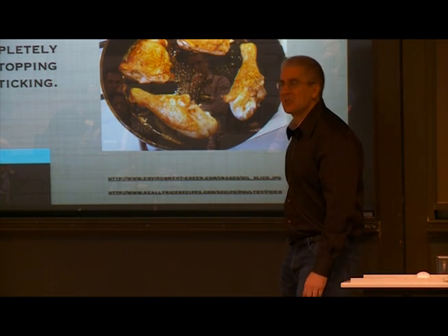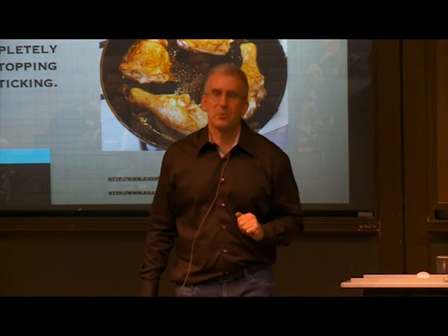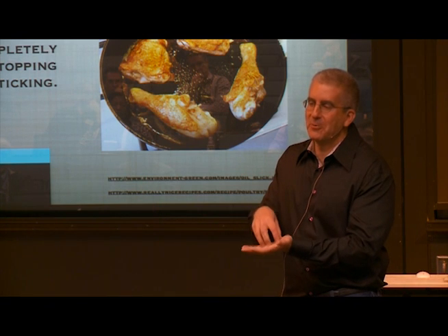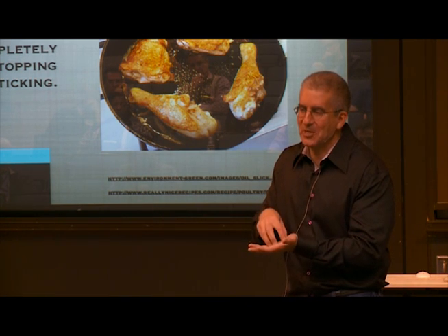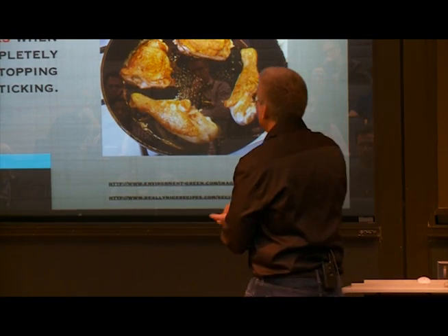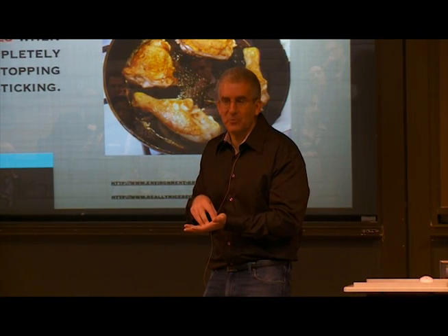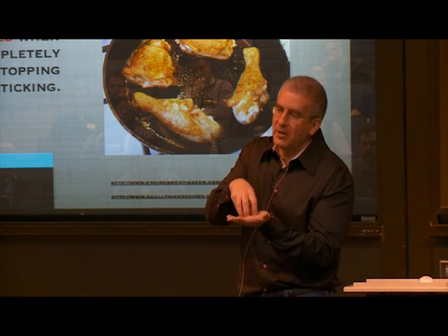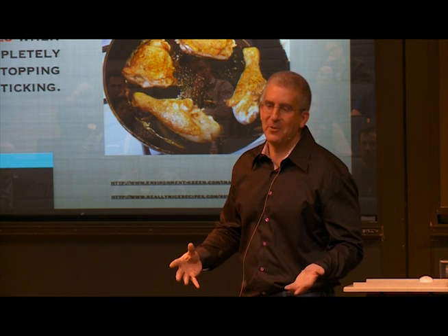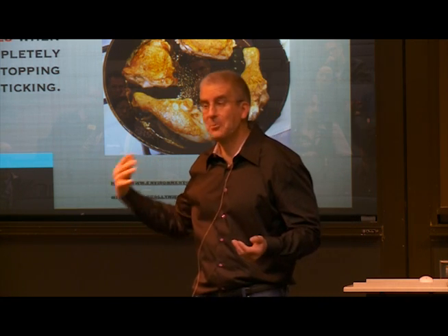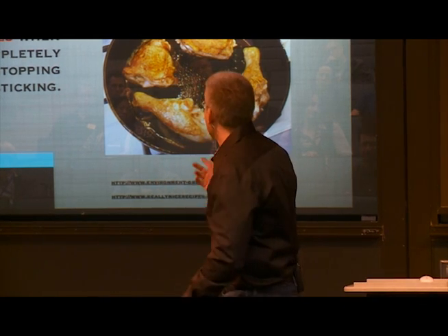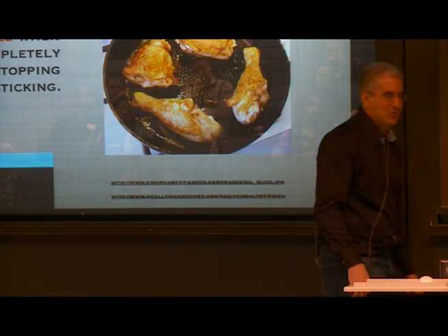The second instance is when you cook something. When you heat oil, the cost of a solid-liquid interface goes down, that is, the energy associated with it. It also turns out the cost of a liquid-air interface goes down. Surface tension reduces. So heating things up tends to reduce these interface costs. If you pour a drop of oil into a frying pan and turn the heat on, it spreads out to be a very, very thin layer. This is great because it provides a lubrication layer between the food you're cooking and the solid pan. So cooking makes use of surface tension also.